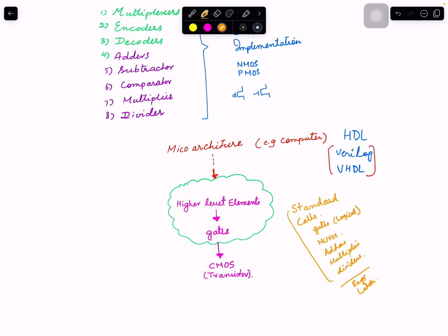So you really optimize certain key blocks. For example, I can take a simple full adder, where A is coming in, B is coming in, Cin is coming in, and it will have a single output S and a carry. I will really optimize it at the transistor level. So I will create different gates made of different transistors, interconnect them and optimize them so that I create a very compact, very high performance, very low power design, and then I will use that as my standard cell.